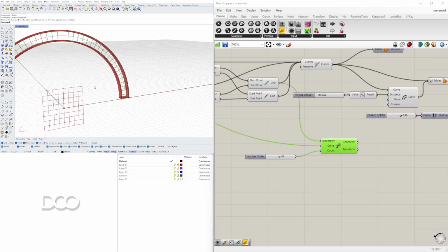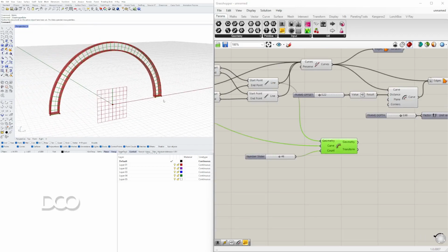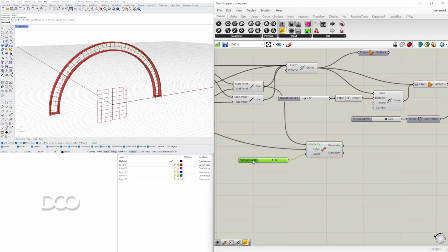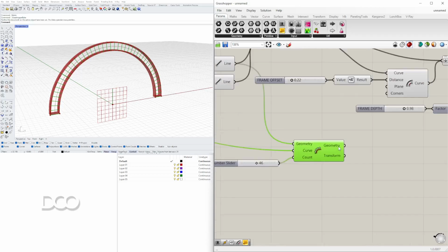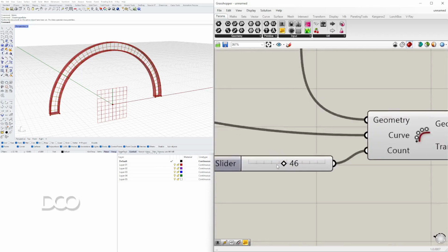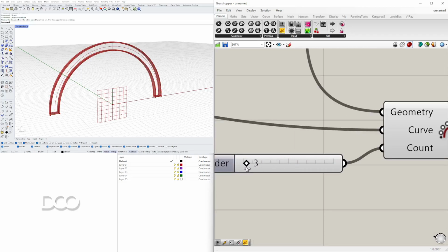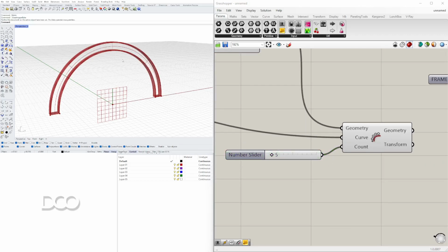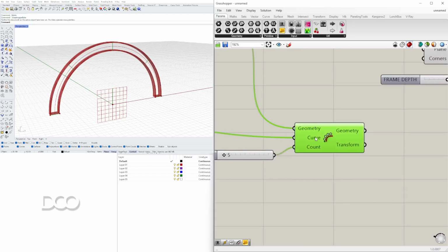And so to select all of them except for those, there are a few tricks that we can use here. Let me share with you the way to do this. So if we go here under geometry, let's lower this to like 5. So if we have 5 subdivisions, well, we technically only need 1, 2, and 3, and the first and last we don't need.